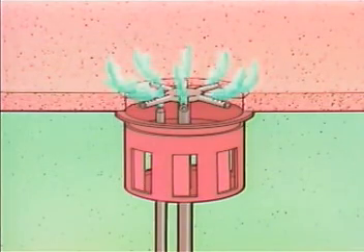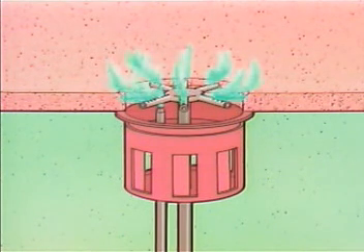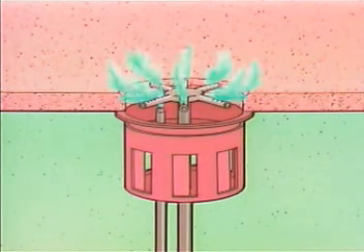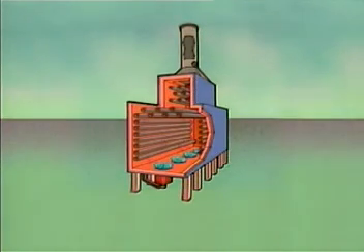Radiant heat transfer is not the only type of heat transfer that takes place in the radiant section of the furnace. Some convection heat transfer also takes place. When the burners are firing, the gases near the burners are the hottest. As these warm gases mix with the cooler gases surrounding them, heat is transferred by convection.